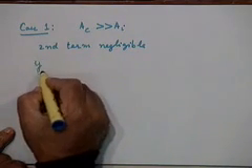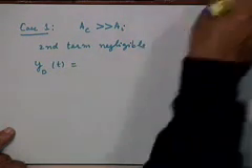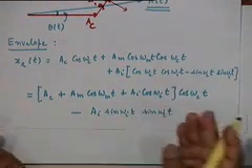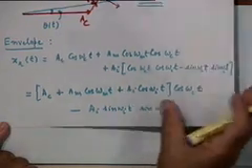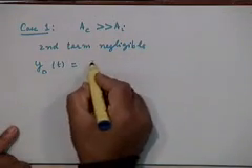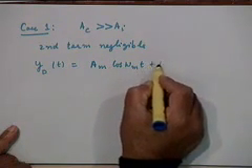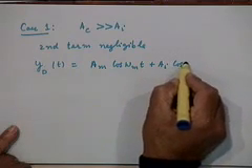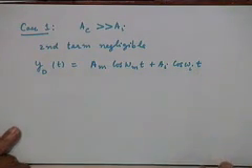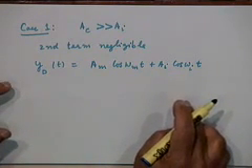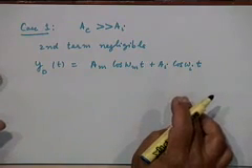and your demodulated output, if you forget the DC component, right, A sub c will be the DC component in the demodulated output, which is of no consequence, we can ignore that, will be A sub m cosine omega mt plus A sub I cosine omega it, which is perfectly fine. This is precisely what we got when we used the coherent demodulator. If you remember, some time ago we discussed that, right? This is precisely the output that was produced by the coherent demodulator.